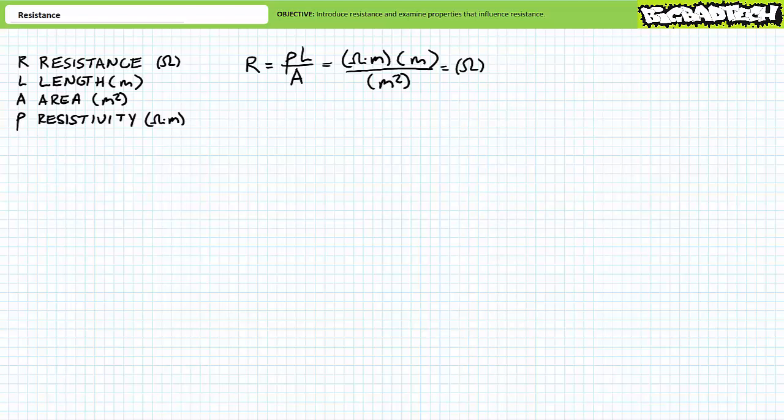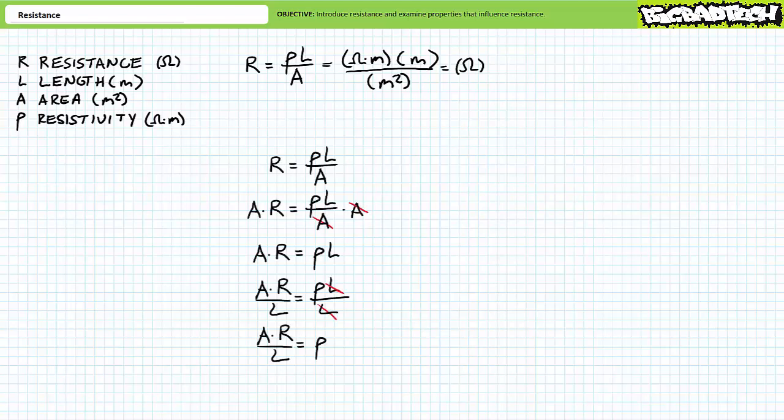You should be slapping your head right now in sheer amazement because I just tricked you into doing math without realizing it. I know we didn't use any numbers at all, but we just derived the resistance formula just by thinking about it. Beyond directly calculating resistance, algebraic rearrangements of this same formula can be used to solve for individual properties. For example, if you wanted to solve for resistivity, given known resistance, known length, and known area, an algebraic rearrangement of the resistance formula demonstrates the resistivity is resistance times area divided by length.